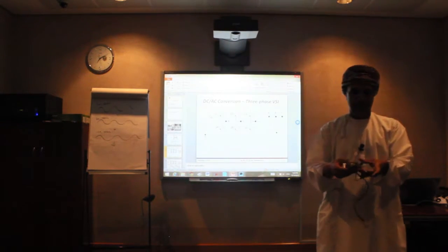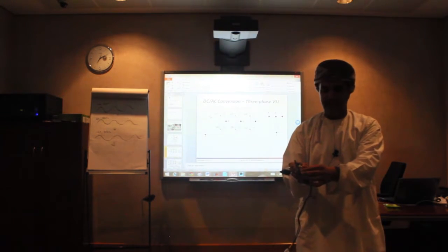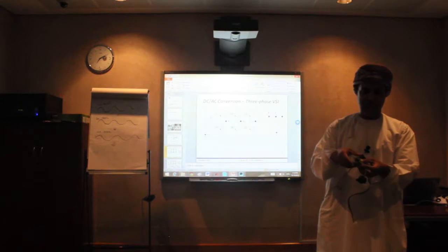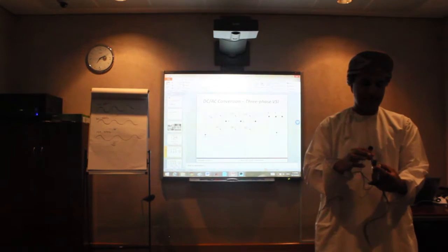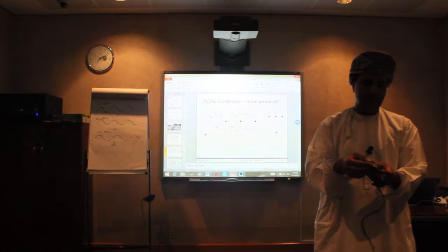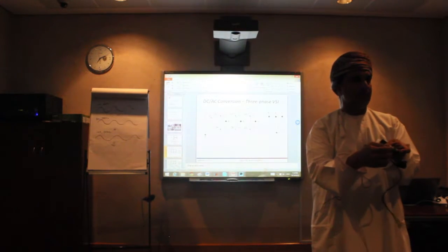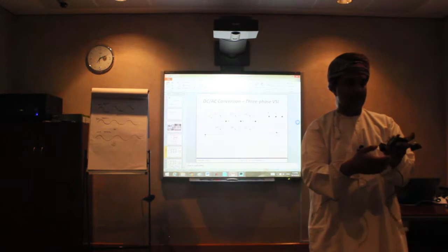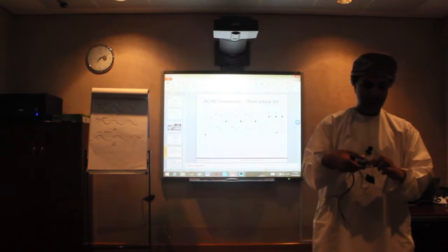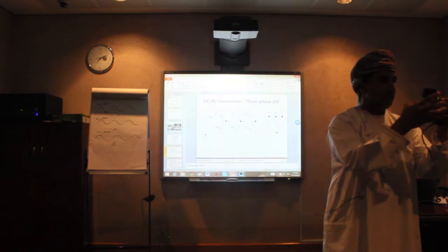Okay. So look here. If you look at that one, you see that these are the 4 transistors, those switches, in order to convert the DC to AC. And on this side here, I think there is a buck converter to convert the DC voltage from 12 to 5 volt for a USB connection if you would like to charge a mobile or something like this. And also you can see the components of this one, and how the signal is generated and everything. You can see it's integrated inside those chips. So everything is here, and it's one piece.